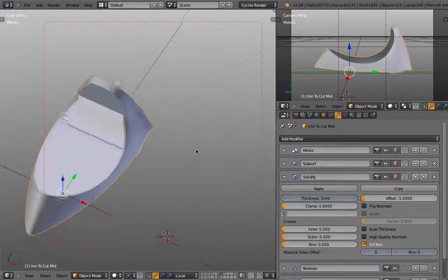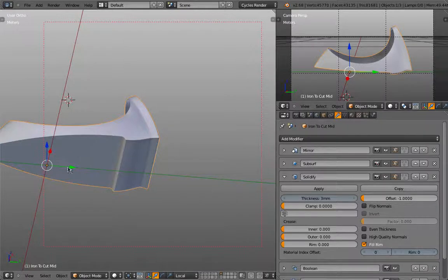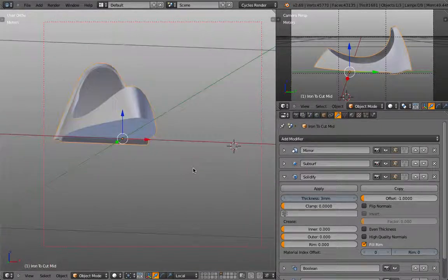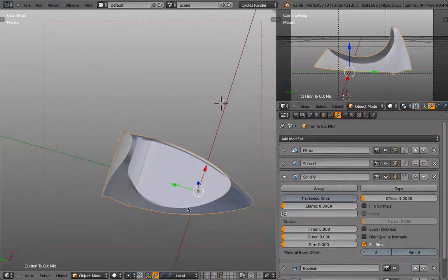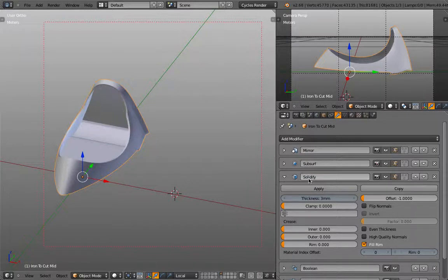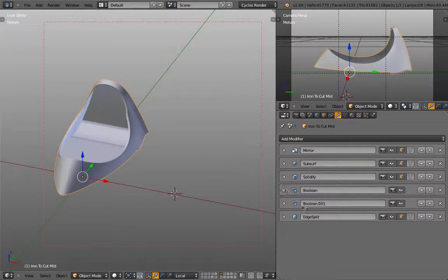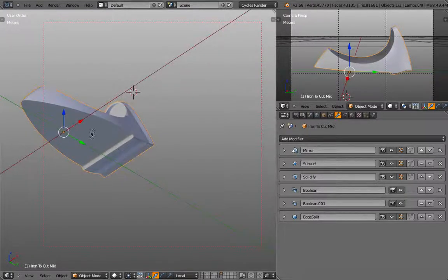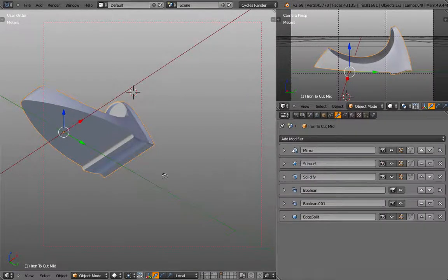And hold on, let me also bring that Solidify modifier back, because you see everything is nicely cut, but right here the surface actually, that bottom part shouldn't be there. We should be able to see through it. And whenever you use a Solidify modifier together with Boolean operations and you get something like this, chances are high that the polygon mesh the Solidify modifier generates simply is garbage.